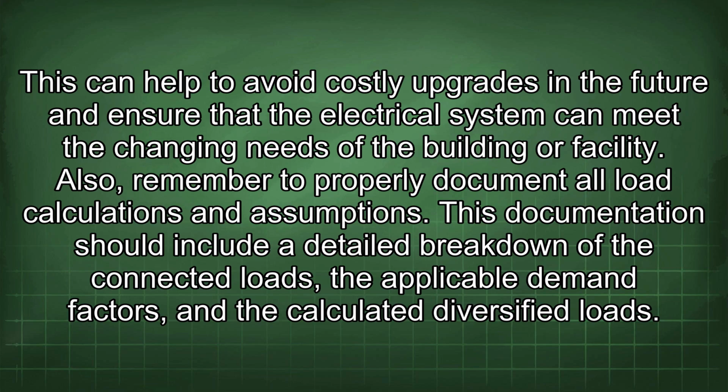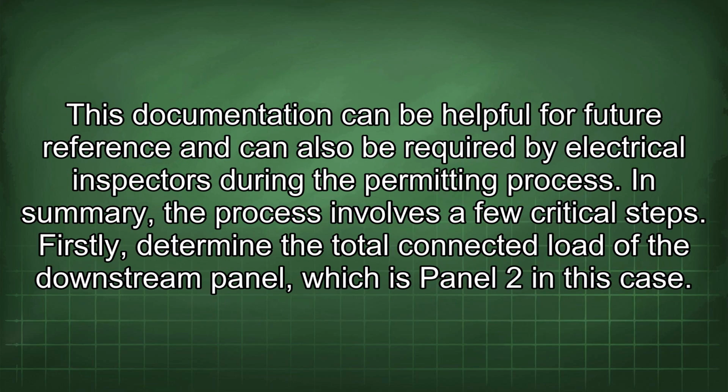Also, remember to properly document all load calculations and assumptions. This documentation should include a detailed breakdown of the connected loads, the applicable demand factors, and the calculated diversified loads. This documentation can be helpful for future reference and can also be required by electrical inspectors during the permitting process.